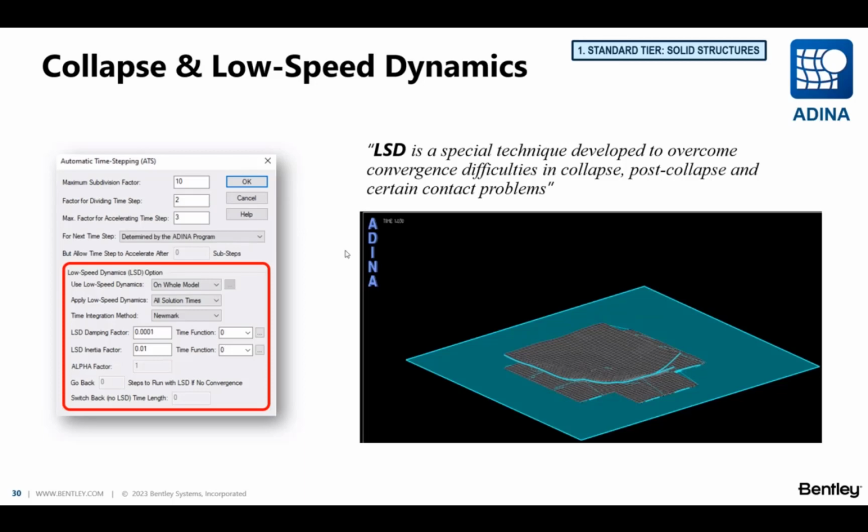So in general, we're talking about those problems that are difficult to converge. We have post-buckling behavior, large plasticity, complex contact conditions. So this is useful, for instance, to evaluate structural redundancy, the ability of the structure to form alternative load paths when a member fails. This could be because we're suddenly missing a column or in the event of fire. There are different scenarios.